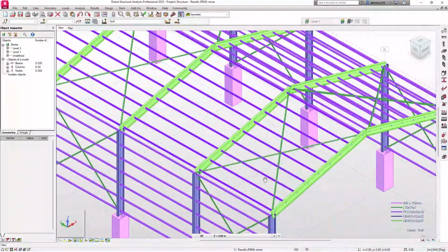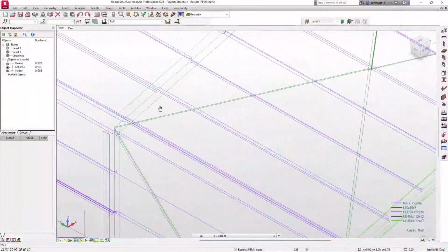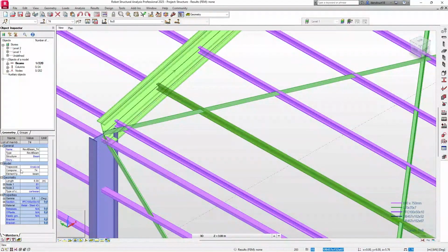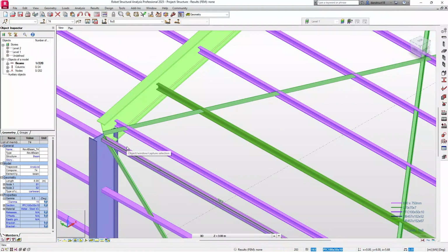Now I'm going to go over here to one of the Purlins as a sample. I'll click on it. And under the gamma, I'm going to go ahead and expand this. I'm going to give it a gamma of 15, which is the same slope as our rafter. There we go. Now press enter. So you can see it slopes in the wrong direction, so it should be -15 actually, or 165. So let's try 165, and now you can see it is in the right direction.